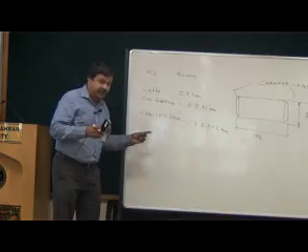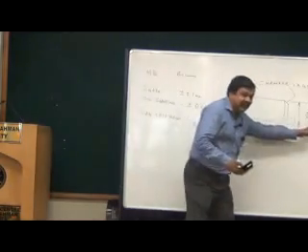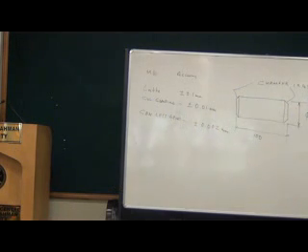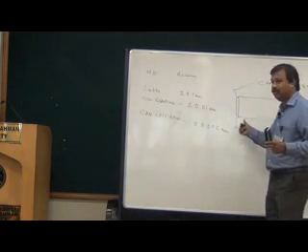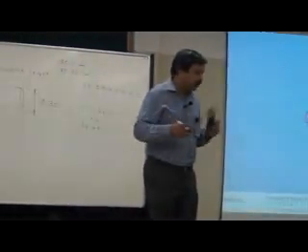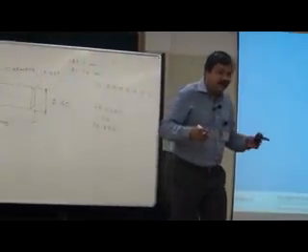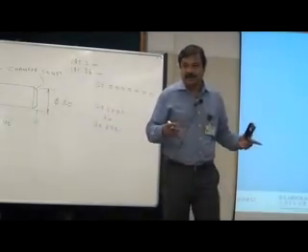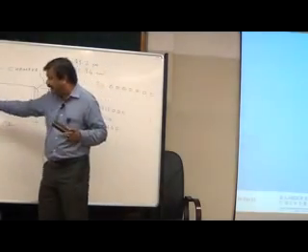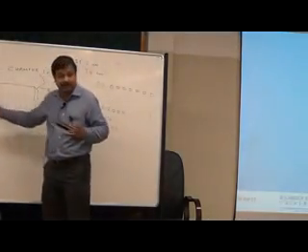Now the basic question is, if I blindly say 30 mm, the production engineer doesn't know in what machine he must finish this particular component. Whether it is to be machined in a lathe, or in a cylindrical grinding, or in a centerless grinding, he doesn't know.